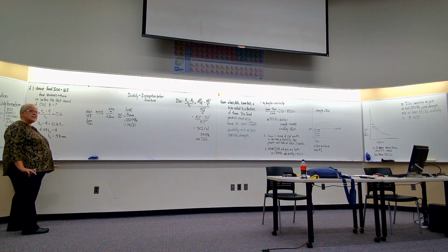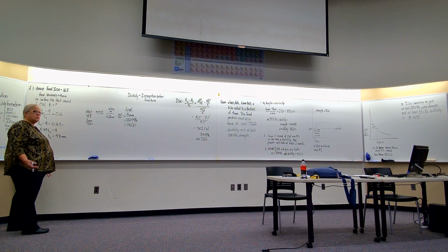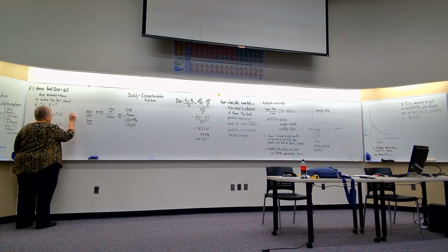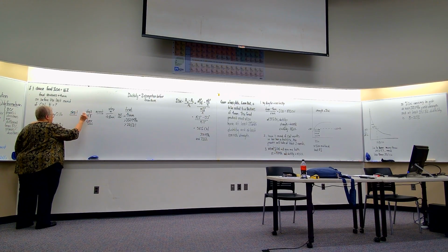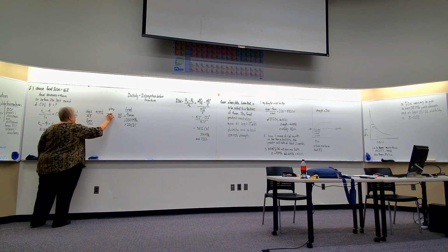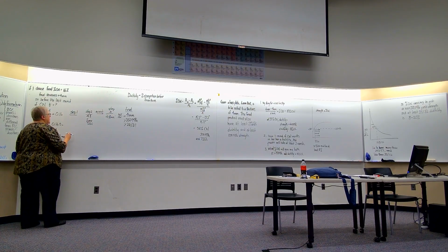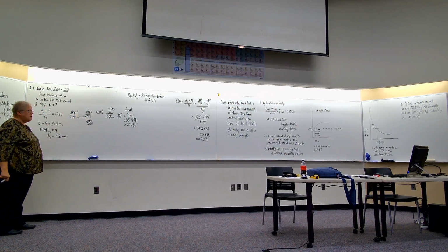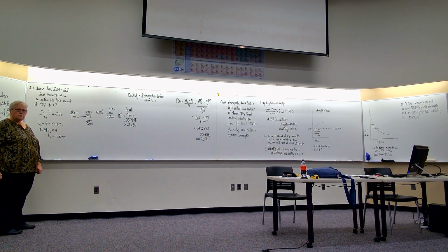Now, if I'm not giving you a restriction about how much cold work I can put in between, I could say, okay, this is going to end up being step 1, 2, 3. So step 1 is to go from 6 millimeters to 4.8. And it will have some amount of cold work in it, right?